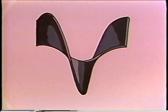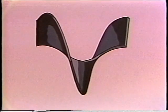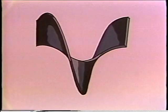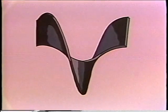In addition to helical conveyor flighting, most manufacturers make what is known as sectional flight screw conveyor. This type is fabricated one pitch at a time. These are then welded to a shaft and to each other to make a continuous screw.